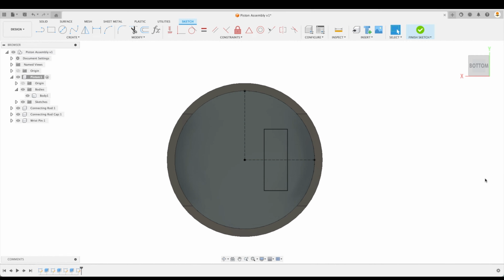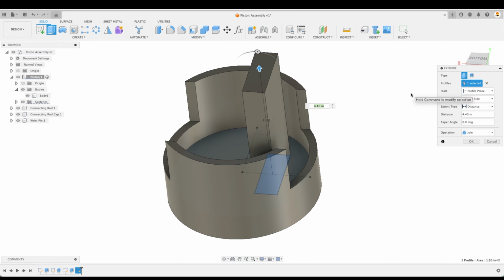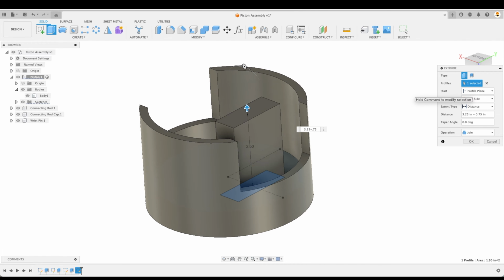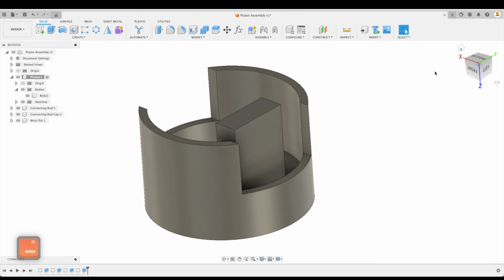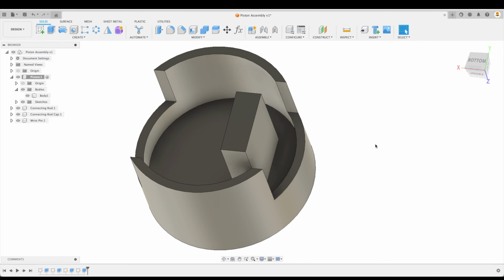Let's finish that sketch. Now we can extrude this. And this is going to be 3.25 minus 0.75. And this is slightly taller than the piston, or extends slightly past the piston, I should say. And we're going to join that. And now we can simply mirror it to the other side. But what would be better than mirroring it and then having to do all of our different fillets and everything like that? We can actually fully finish that lug and then mirror it once it's complete. It just saves a lot of effort with creating 2 sets of fillets and all of our other features.